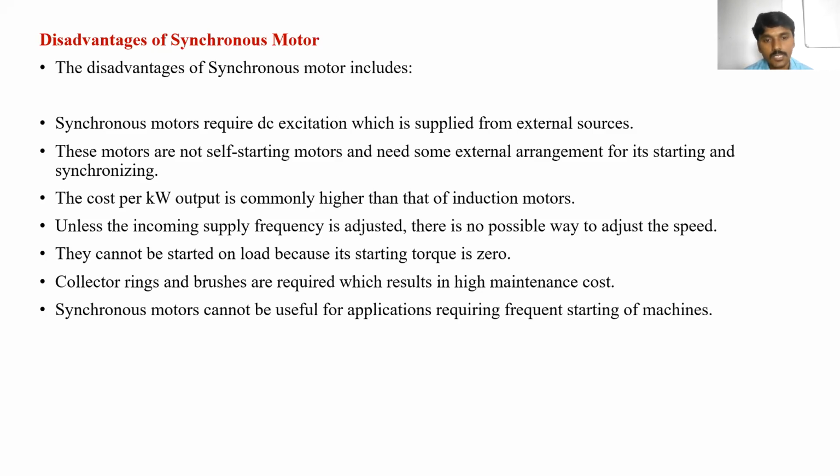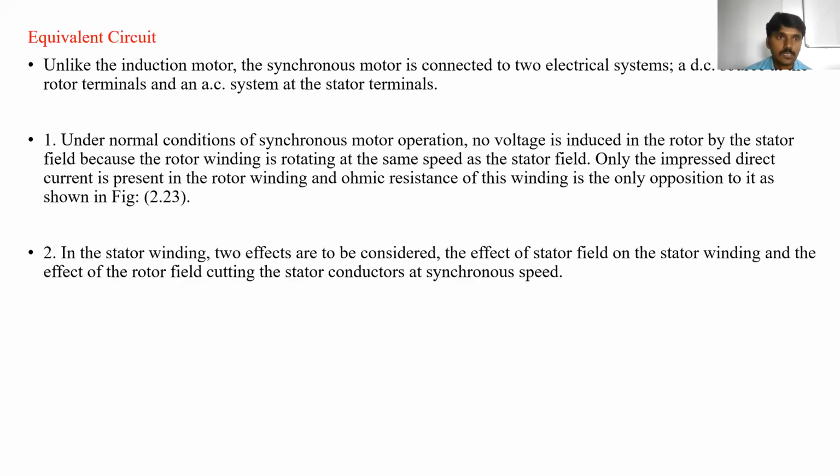Synchronous motors cannot be useful for applications requiring frequent starting of machines. So wherever we are starting the machine again and again, frequent starting, that is, wherever we want to start the machines again and again, the synchronous motor is not perfect for those places. Okay, so these are the disadvantages of the synchronous motor.